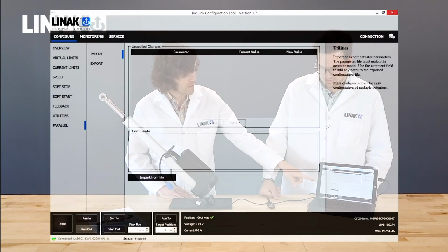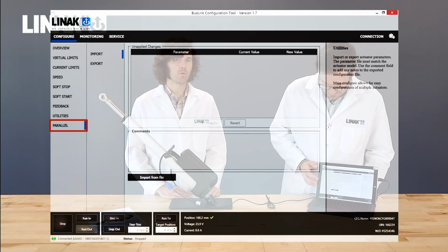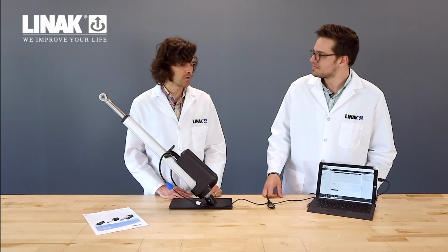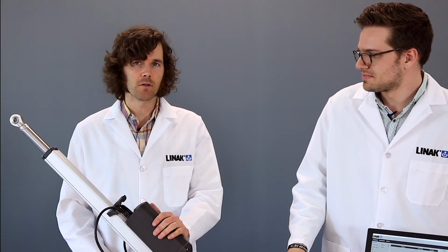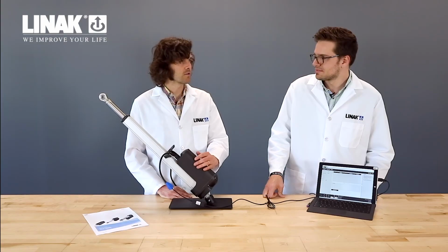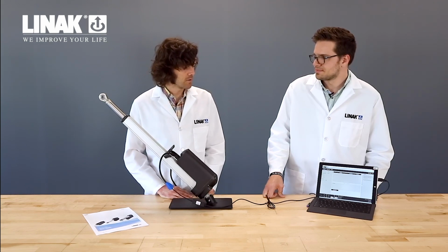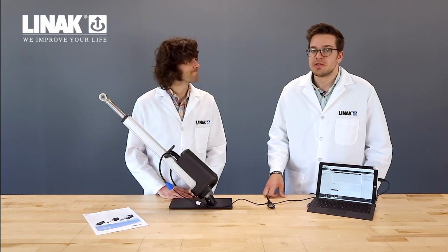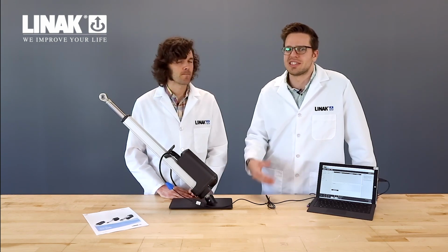And there's actually one more tab at the bottom on the side here that you can select the number of actuators that you want in your parallel system, selectable from 2 to 8. But with the IC Parallel, you are not actually able to use positioning feedback, so that aspect of the menu is taken away. That's right. The positioning feedback in IC Parallel is actually reserved for the parallel functionality to speak between the actuators and communicate that signal. Those leads are actually taken out.